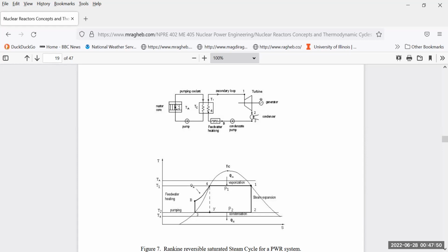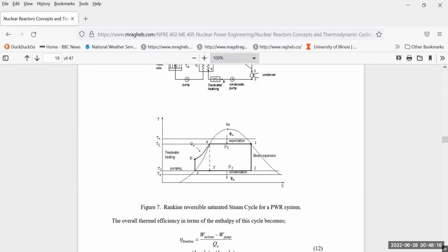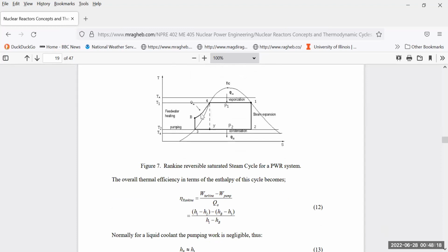You don't want to produce steam in water that would be sloshed around by the waves in the ocean. So you take the pressurized liquid in the pressurized water reactor and take it to a heat exchanger, exchange the heat there to turn it into steam, and that's the steam that goes to the turbine. So you have here in that case some forms of unavailability between the temperature at which you are causing vaporization and the temperature at which you are producing condensation.